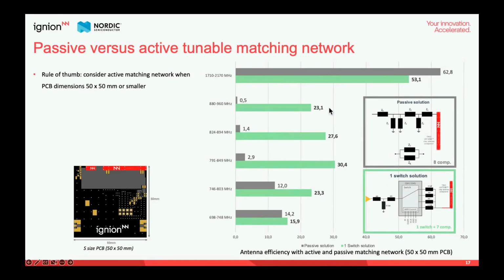So you can see that you have these two options: increase the ground plane if you can, and if not, use this tunable solution to match only at the frequency bands you want to operate. And this is something easy, because it can be engaged, and all the protocols are standard with the Nordic nRF9160. So next, please.